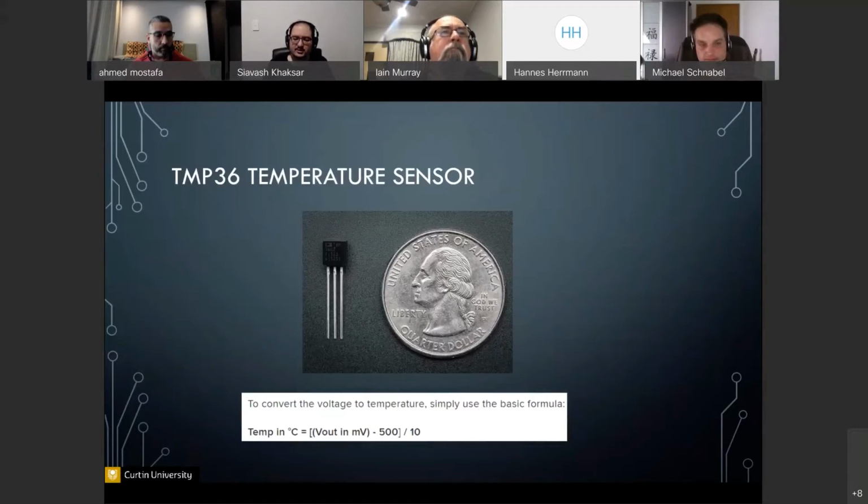This is a temperature sensor, and this is a very good example of what the term raw data from a sensor means. It's raw data because it's at the stage before any processing has been done on the sensor data, or any filtering, or any conversion to a real life characteristic. Here, the actual value we're reading is a change in voltage, and then we pass it to this equation to convert that to an actual temperature in centigrade.